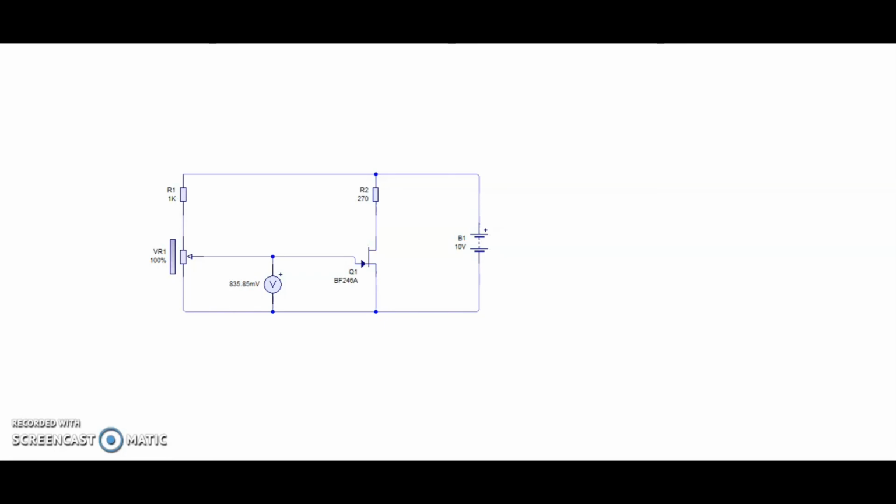Here we can see it is an N-type channel, where only electrons are used. So this JFET operates in depletion mode, which means the control voltage at the gate terminal will remove the carriers in the channel, and then the transistor will conduct from the source terminal to the drain terminal.